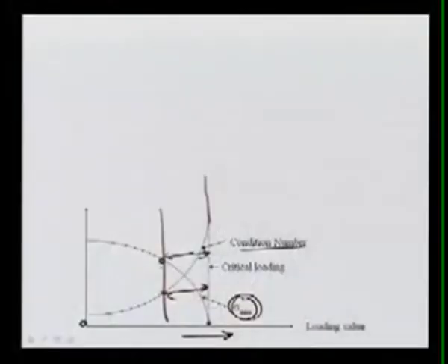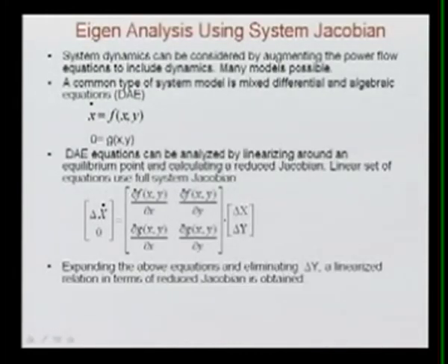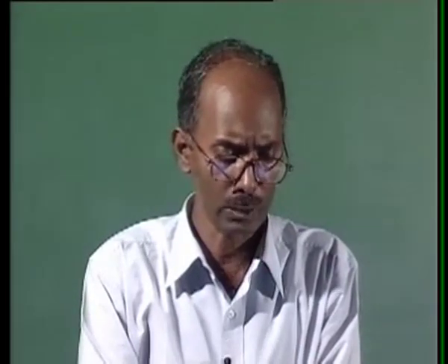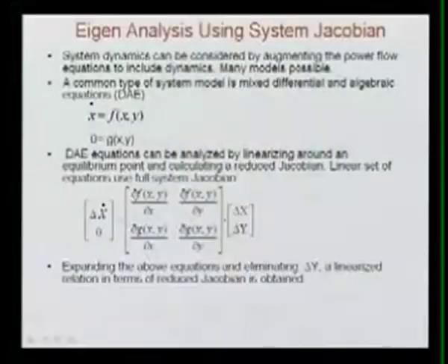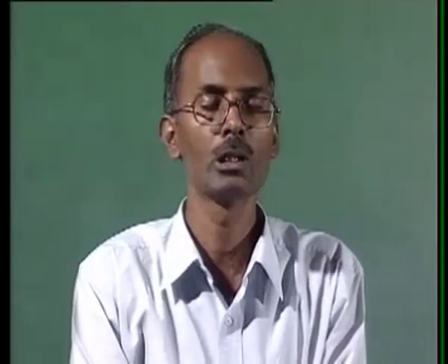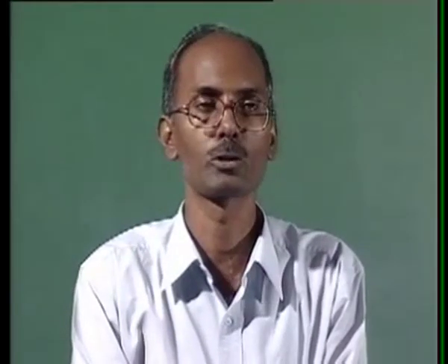This approach is known as the singular value decomposition approach. Another approach, which I was explaining, is the eigenvalue analysis approach, and that again comes under the repeated power flow method. In this, the system dynamics can be considered by augmenting the power flow equations to include the dynamics: the generator dynamics, exciter dynamics, load dynamics, and whatever other parameters you want to include.